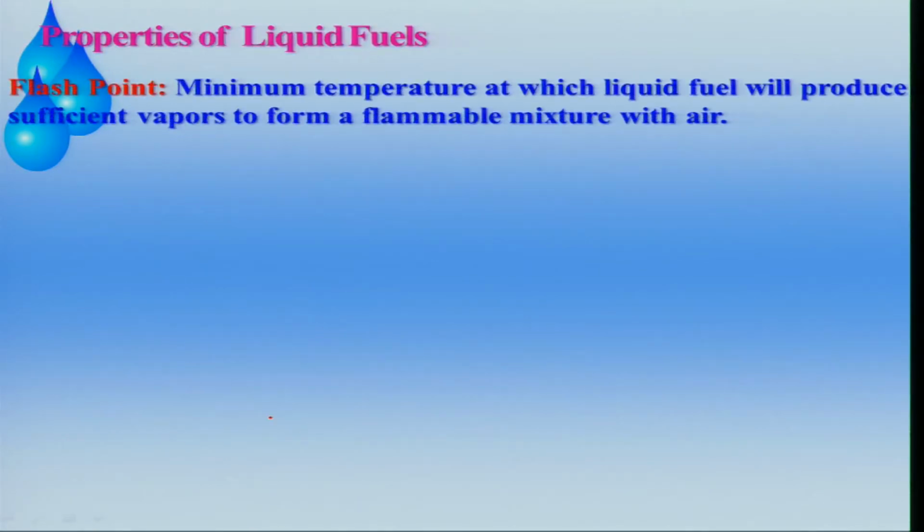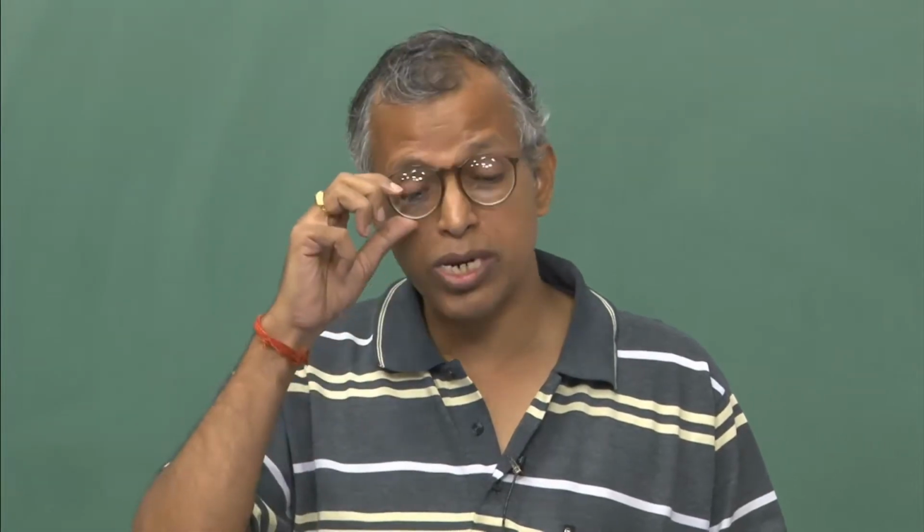There is another very important point, that is the flash point, which is basically the minimum temperature at which a liquid fuel can produce sufficient vapor to form a flammable mixture with air, right. That means it will vaporize, as a result there will be a flash, and then it will discontinue again, right. That means it is a phenomenon which remains for a certain time. So, it is very important from the storage point of view.